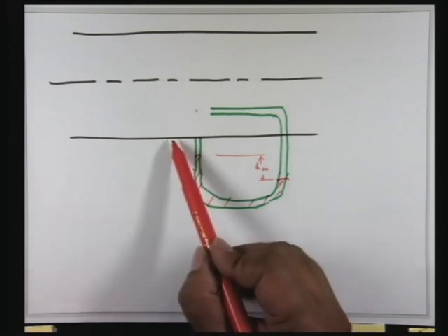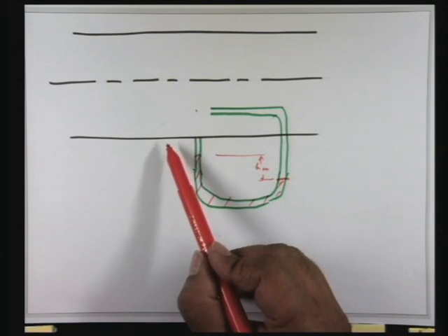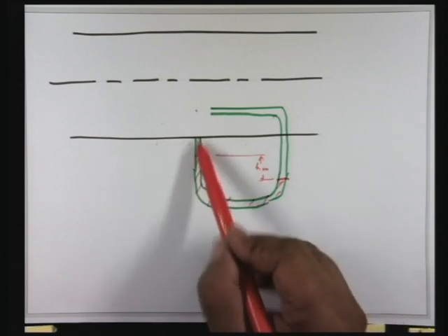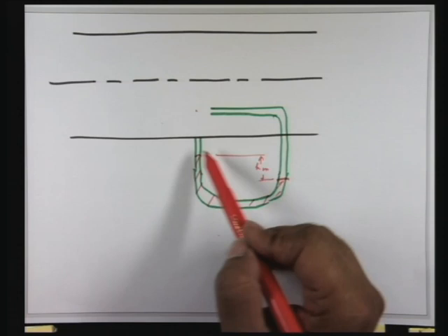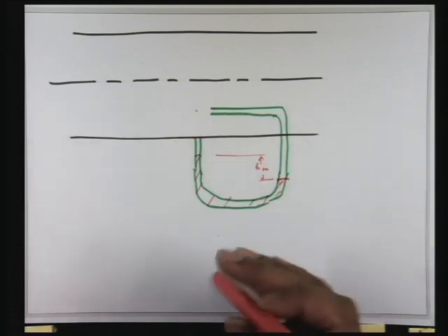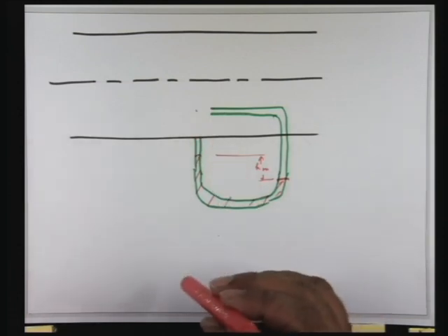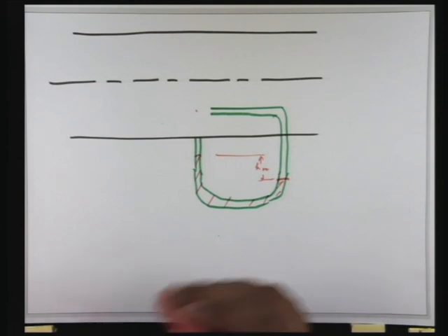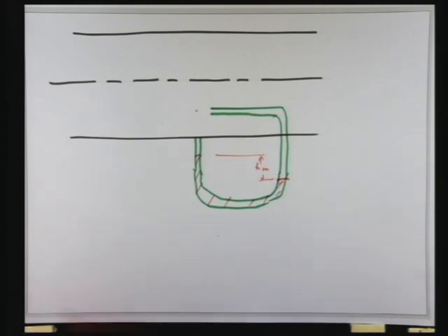Because once they are entering into the left limb of the U-tube manometer, they are not moving. They don't have any velocity. There is no velocity component along the tube axis. No, zero velocity does not mean that the pressure will be the static condition. That is why I defined the stagnation pressure earlier.